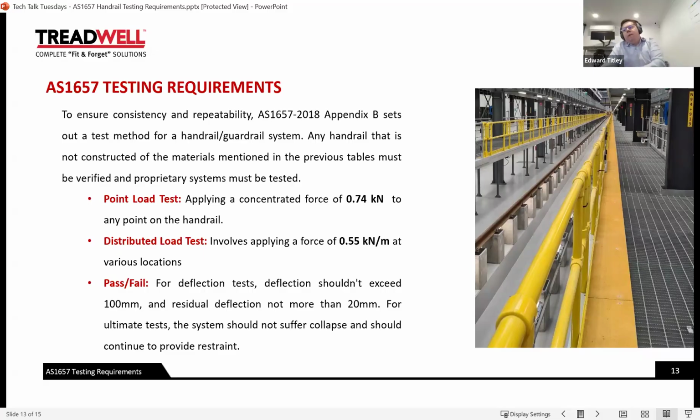The second thing is we often have queries around the removable handrail, which is understandable, as to why that's necessary or beneficial, but there's an easy pitfall with that, which is it's a very fine line between having handrail that's easy to remove, whether it's something that's removed for maintenance, or in this example here, these handrails are in some locations removed when a train's brought in to allow access to the train for any sort of maintenance and so on, and then before the train leaves, the handrails are reinstalled to stop anyone from falling from height.